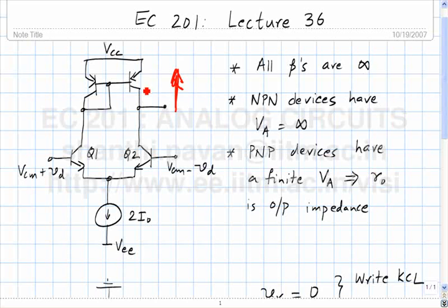It will push. Come on guys. If this node potential goes up and up and up, eventually it will push this transistor out of the active region into its saturation region, causing the gain of the amplifier to fall. Does that make sense? Similarly, what is the maximum voltage here that will still keep this guy in saturation?